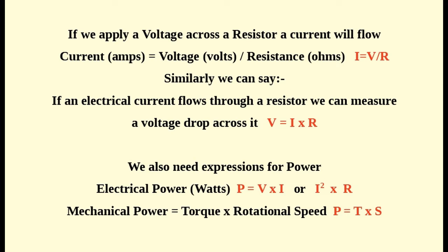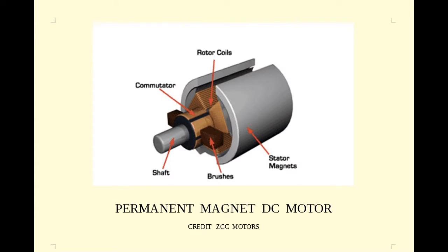We're now ready to consider the motor. The electric 9F uses direct current permanent magnet motors. The rotating part, called the rotor, contains coils, which as it rotates are connected in sequence by a commutator and spring-loaded carbon brushes to a DC supply voltage. The magnetic field that this produces acts against the permanent magnet field in the stator, that's the outer non-moving part, to produce a torque T.